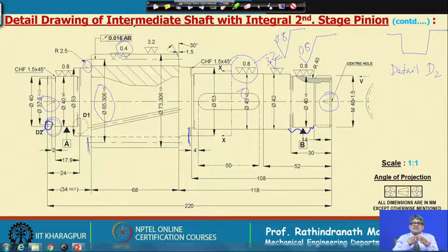They may be slightly inclined, because when we cut the gear, the shaft is put into another machine, the gear cutting or hobbing machine. There we have to center it and cut it again, and maybe the table itself has slight misalignment. Also, while machining this shaft, these two ends may be shifted slightly this way and that way.